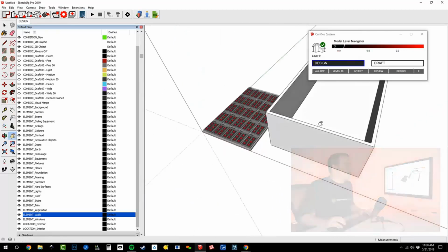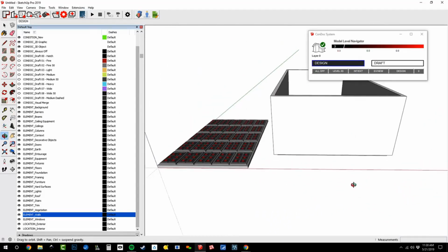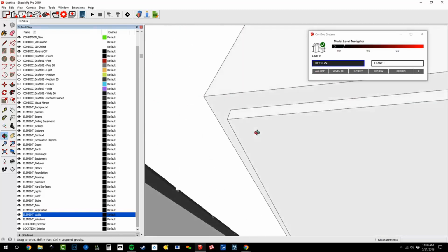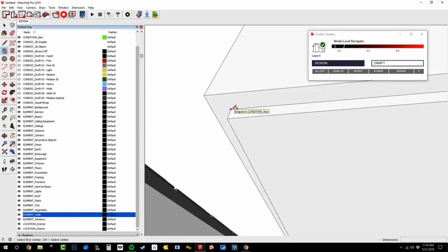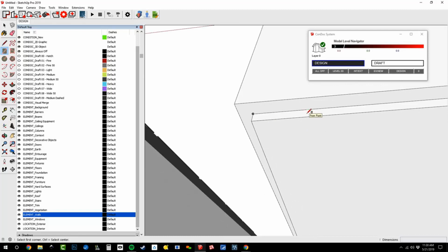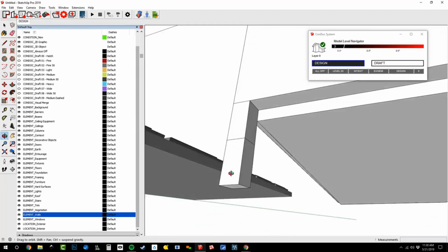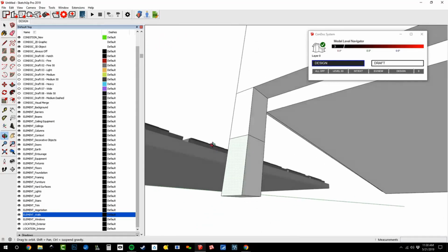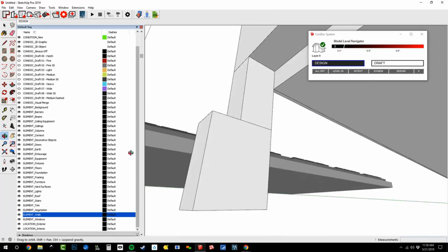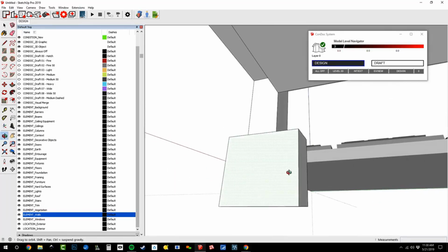So let's keep going. The next thing I'm going to do is let's build our foundation. All right, so to do that, I'm going to start modeling here at this kind of base level. All right, and I'm going to do that cut and paste and place thing I was telling you about. So the first thing I would do, I just need to set up my foundation. I'm going to pull this wall down by, say, 12, and maybe pull it down again by 12, and let's see, I'll pull it this way by 4, and then pull it the other way by 4, and just do like a quick foundation here.